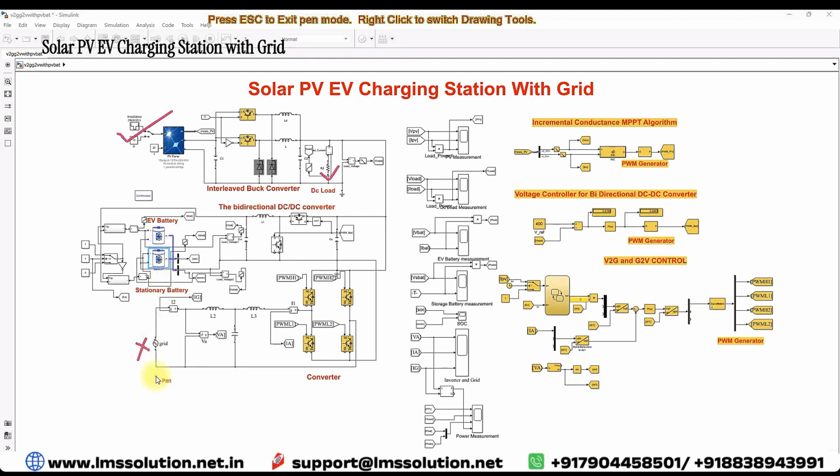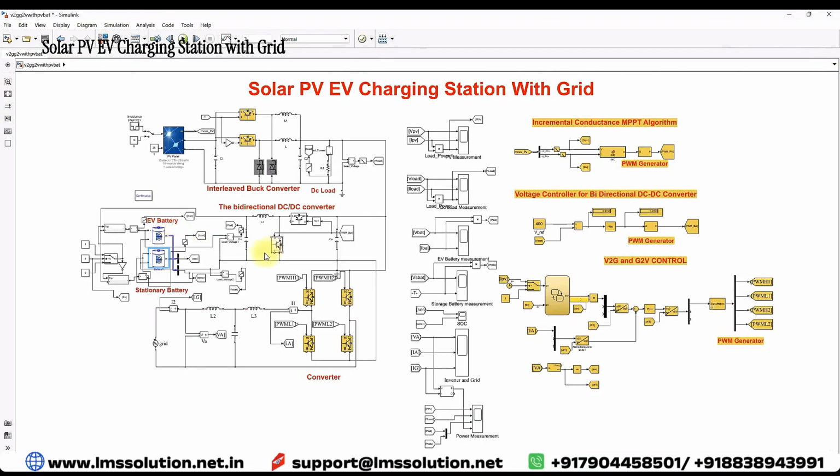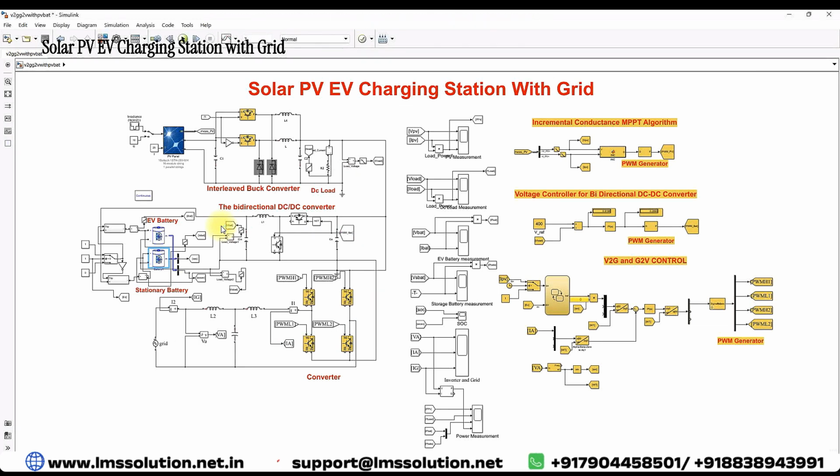When EV is connected, that means this control signal is on, then the EV will be connected with the system. During that, what will happen? When PV has excess power, it will supply this DC load as well as charge the EV battery. When PV is less, or PV is not generating power, then the grid will supply power to the EV as well as this DC load. During this condition, when EV is connected, the grid comes in to supply the power. This is the concept of a solar EV charging station with the grid.